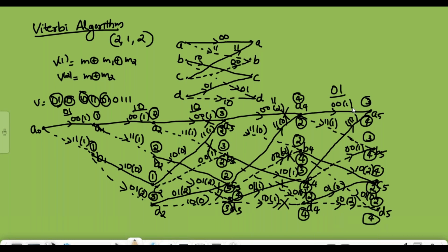Okay, here also we cancel the path with the higher metric, that is 3 is cancelled. Here for this branch, the path with the metric 4 is cancelled. Here the path with the 4 is cancelled. Put a cross mark on that. Here this is cancelled. One more stage can be represented with that. It will be almost complete. Then only remaining is one stage.